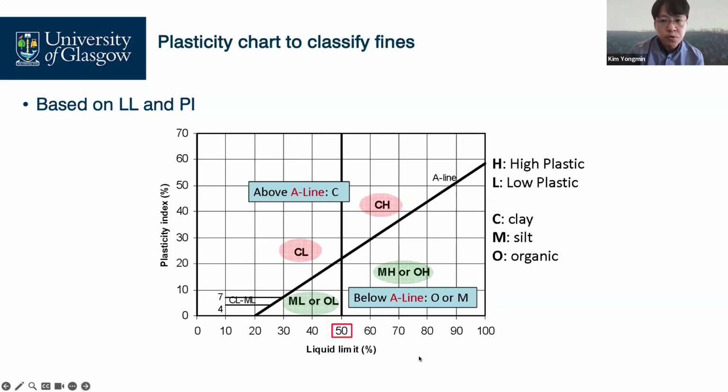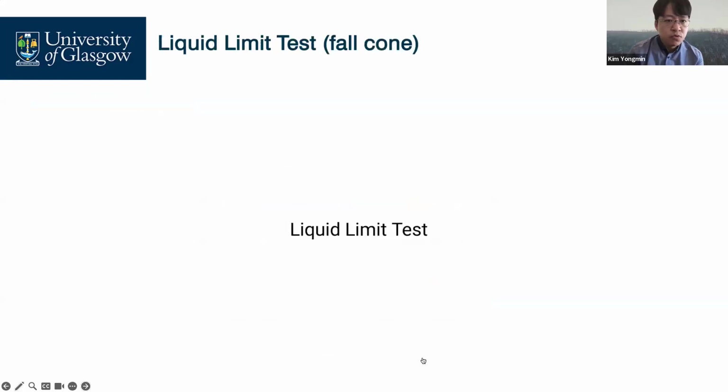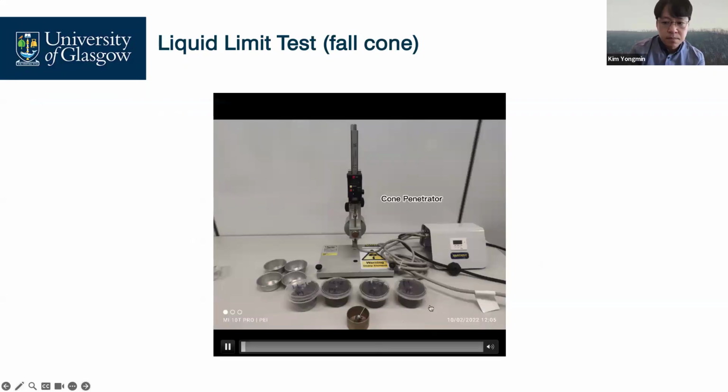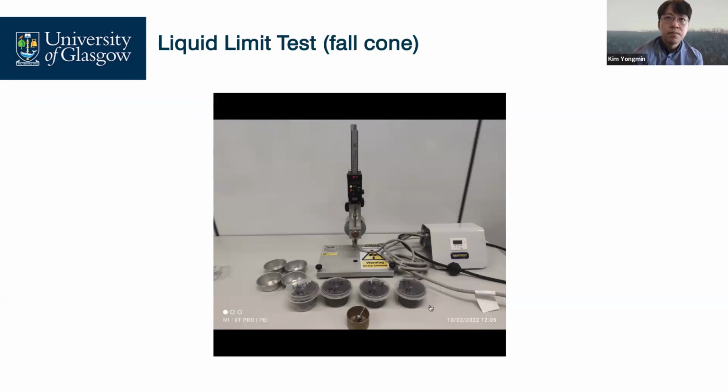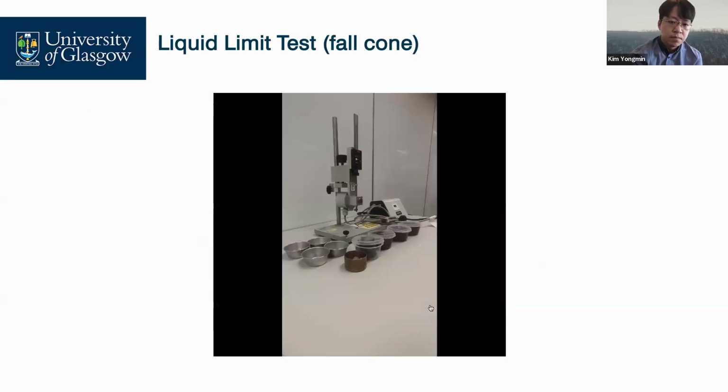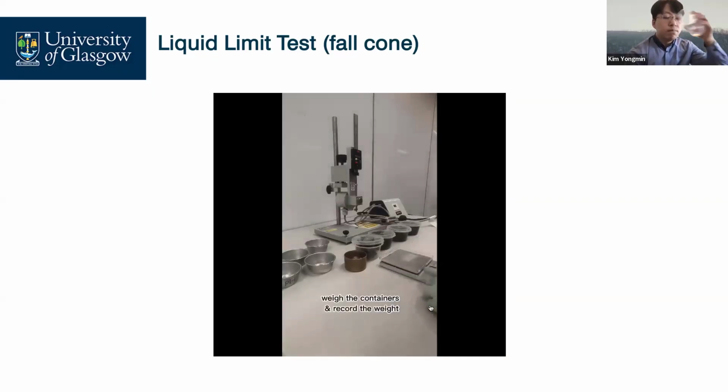So I'm going to show you how to do liquid limit tests. You need the cone penetrator, penetration cone and sample cup, clay samples, and containers. Label the containers. Weigh the containers and record the weight.